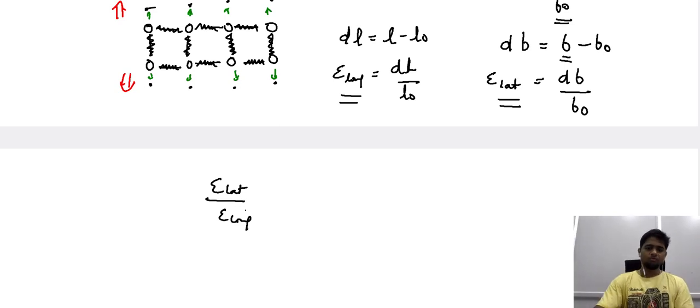Since both these responses stem from a single mechanical condition, we want a parameter that talks about both these different forms of strain. So we have taken the simplest route, just taking the ratio of the lateral strain to that of the longitudinal strain.